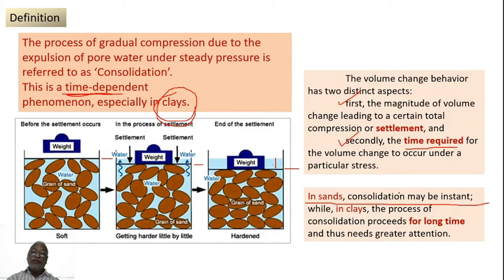So whatever settlement has to happen, happens quickly in case of sands, but in clays the process of consolidation proceeds for a long time and thus needs greater attention. So that is what the whole chapter is about, consolidation, right? So nowhere are we considering sands in case of consolidation. Whenever we say consolidation, it is obviously clays, and that too saturated clays.